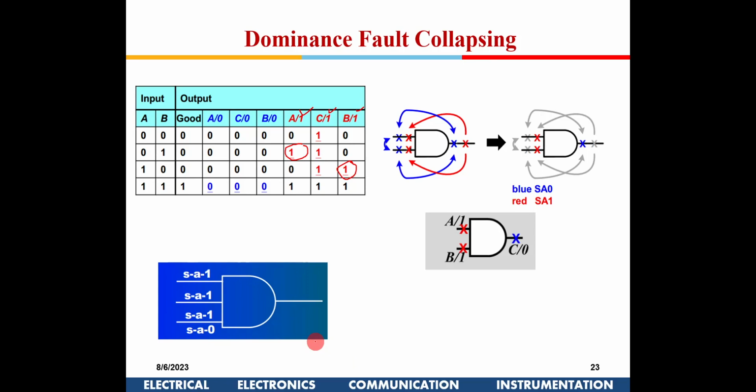Are you in agreement? Because this stuck at 1 is brought here, stuck at 1 brought here, stuck at 1 here. Stuck at 0 are all equivalent, so I can put it anywhere. So in this case, I'm putting it here, for the time being.